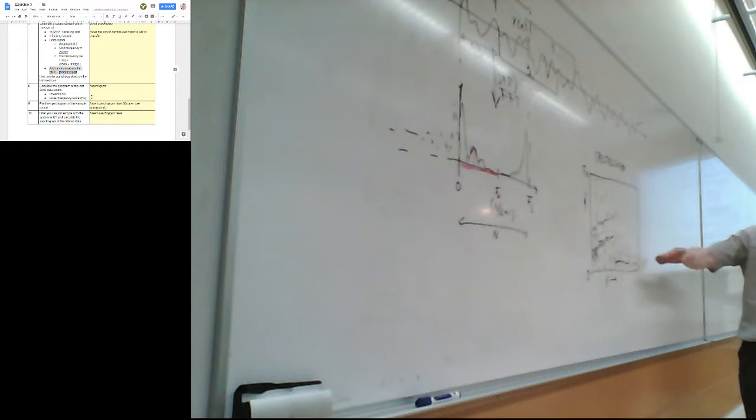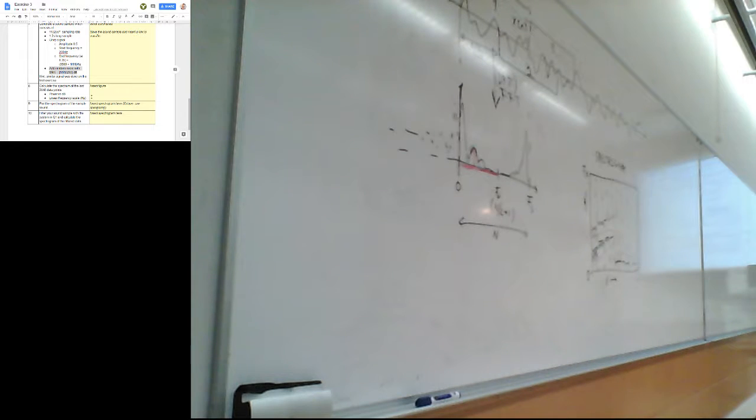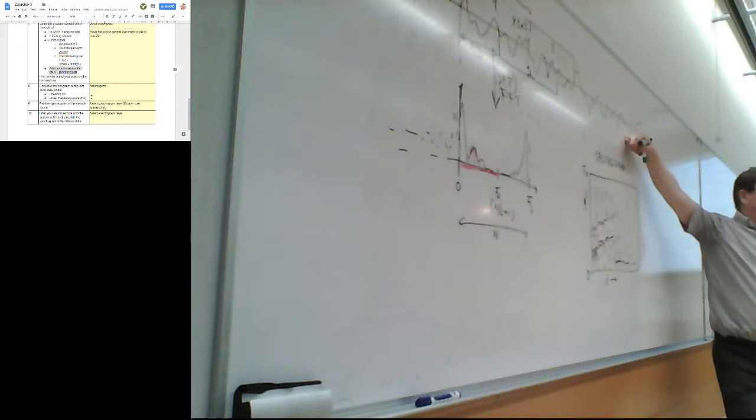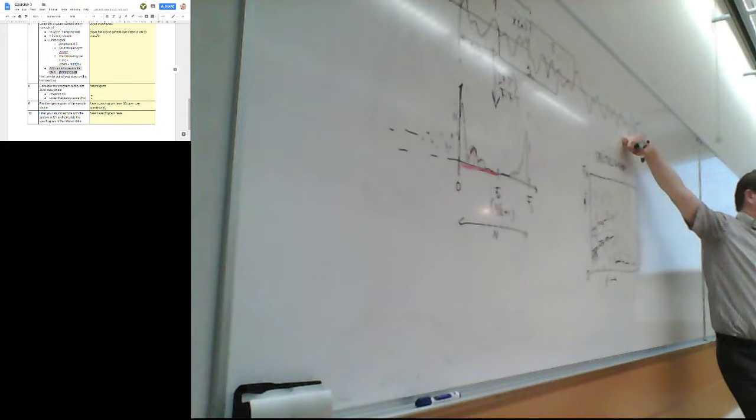So the spectrogram can be used for recognizing bird singing or human voice, for voice recognition. The problem with voice recognition in the time domain is that you cannot really use correlation, since even a slight change in tone will make the sample voices and the real voice look totally random, with no similarity at all.